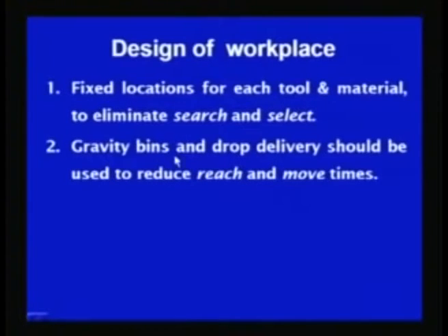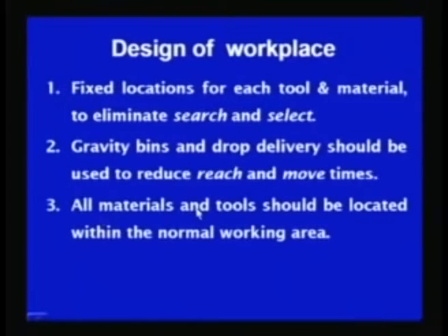And the gravity bins and drop deliveries should be used to reduce the reach and the move related items. These are other steps which can be reduced by encouraging the use of gravity bins and the drop deliveries. All materials and tools should be located within the normal working area. If the distance of the tools and the materials to be used from the body is increased, then it will simply increase the efforts which are to be carried out by the worker.